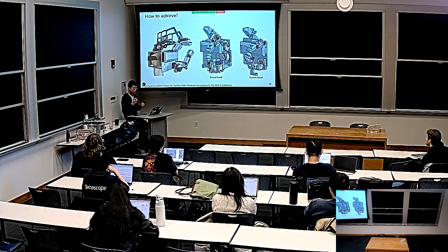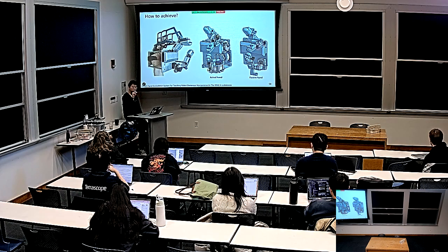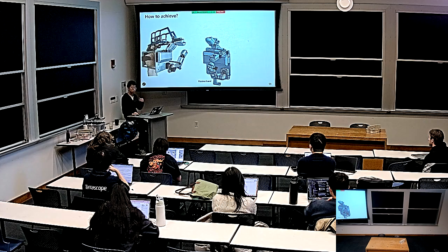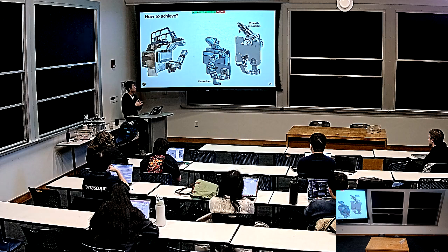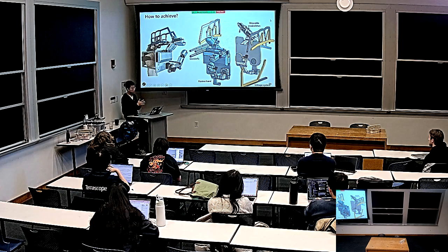So this passive hand can actually have all the sensing that the actual hand would have. It has the full hand tactile sensor, and the joint encoders will encode the joint positions. So now we just need to drive this passive hand when we are trying to manipulate objects. In order to achieve that, we first build a wearable exoskeleton. This part is somewhere you can place your hand. And we then build some linkage systems to connect the wearable exoskeleton and the passive hand.